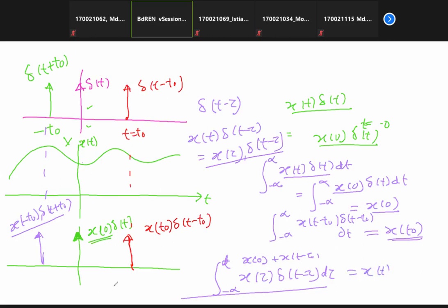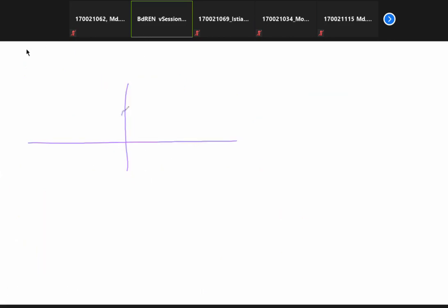This operation is very similar to taking your signal amplitude here, another amplitude there, another amplitude there. All these amplitudes are not appearing at a single instant of time; they appear in tau, which is variable. All these things will constitute your signal. In this way, any continuous time signal can be expressed with the help of this integral.